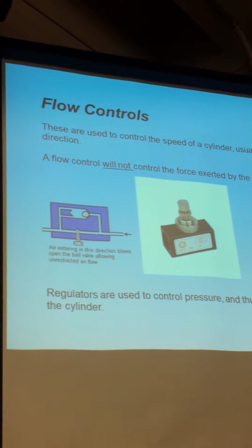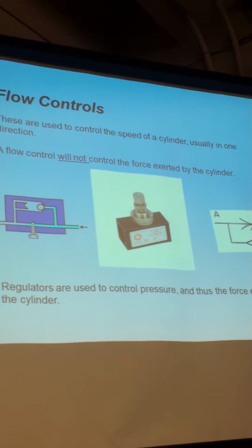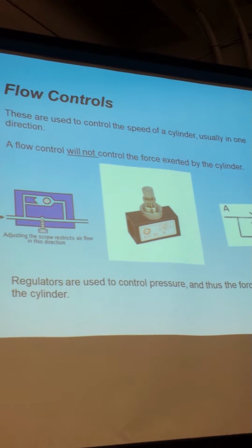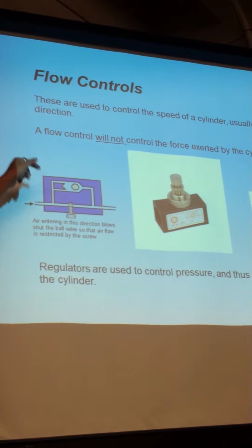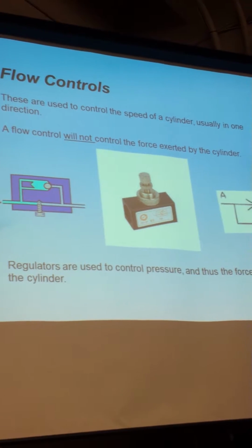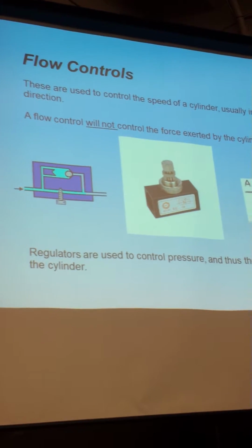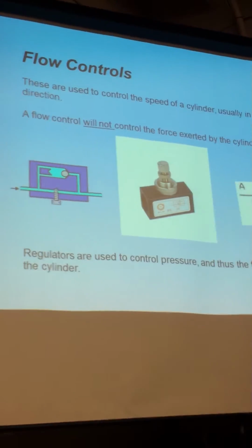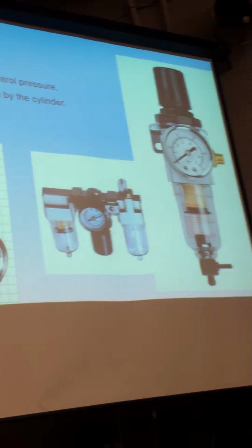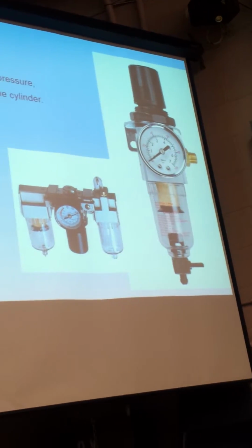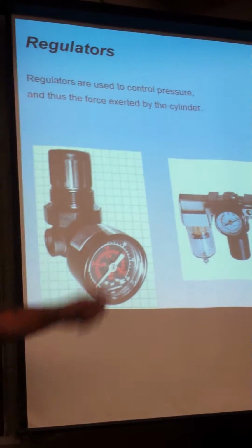Flow controls. Used to control the speed of a cylinder, not the force exerted by the cylinder. Okay, so those 2 points you need to remember. Regulators are used to control the pressure. So we have them all on the boards over there. Some of you are using them, some of you are not. Okay, but the regulators are used to control the pressure.